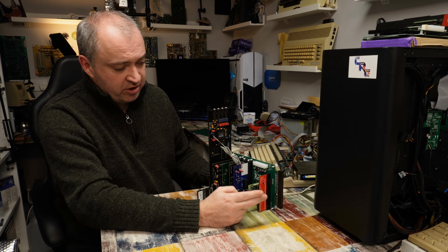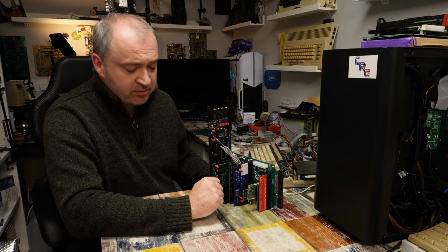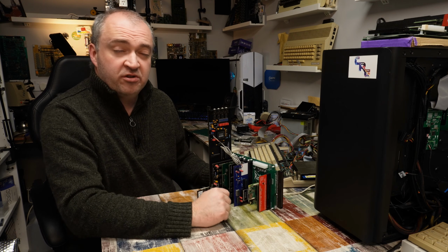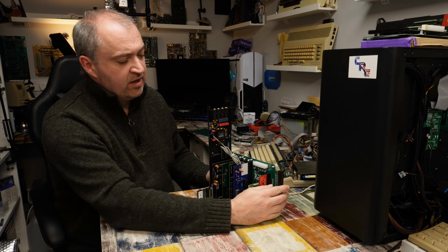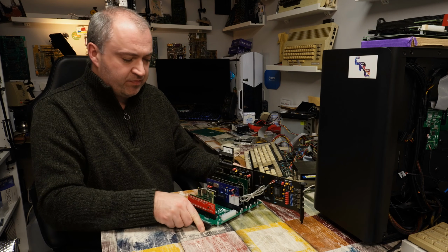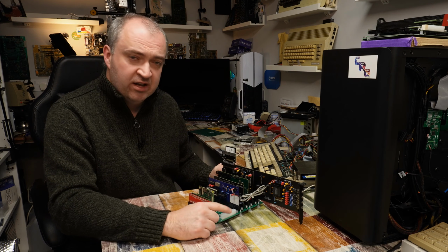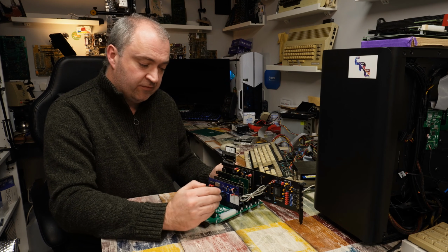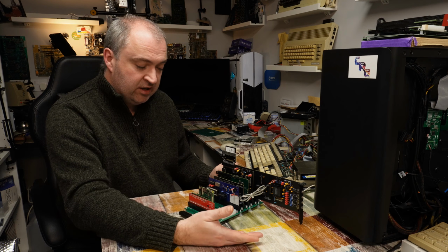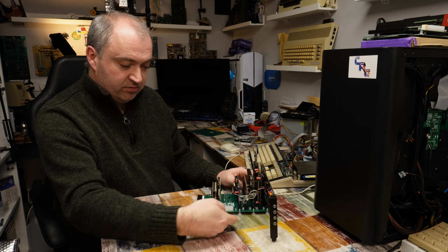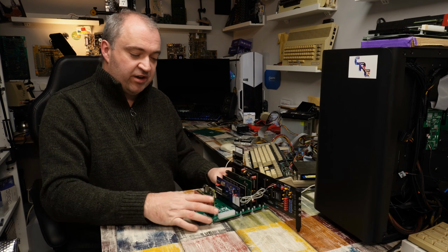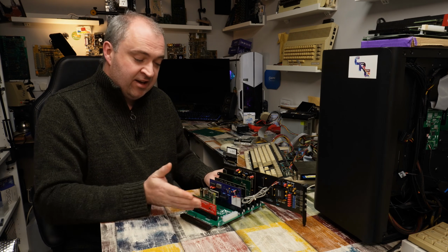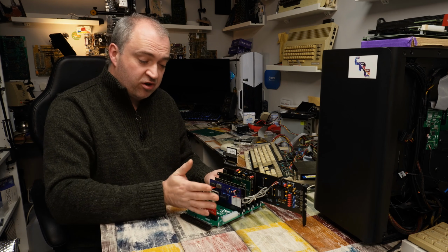We need to sort out those two address lines that were mixed up, and I want to alter some of the text on this. The other thing I might do is change the footprint on the ATX here and the pass-through, and rather than having them vertical, I might make them horizontal, so that you'll be connecting cables in, you know, like that. Just means that nothing then would potentially get in the way of, say, a full-size CPU card.